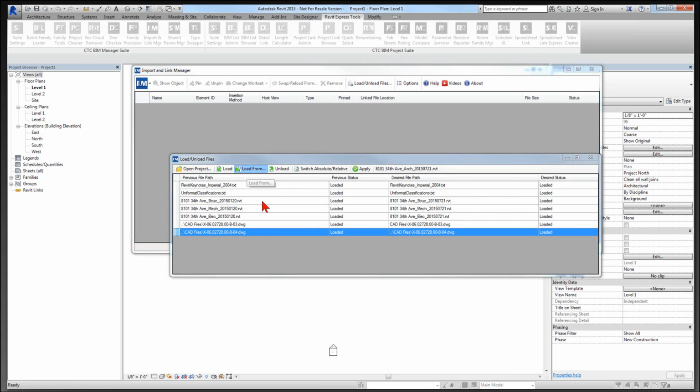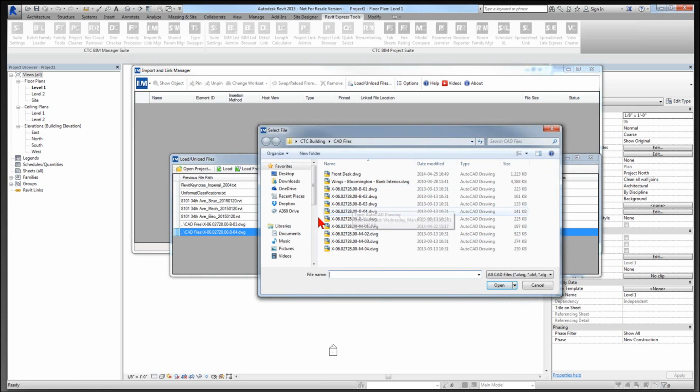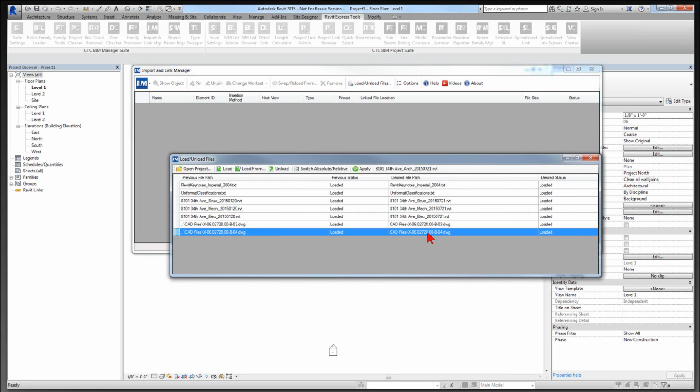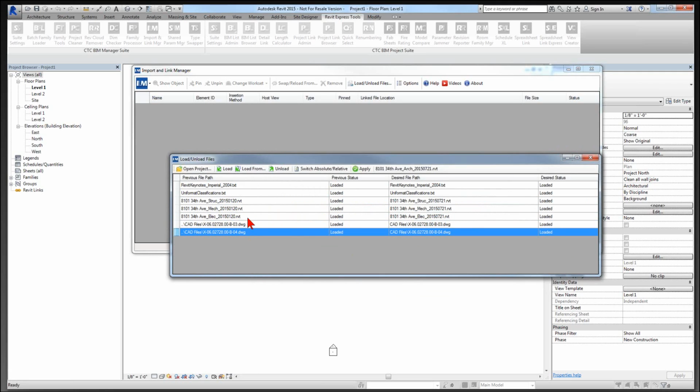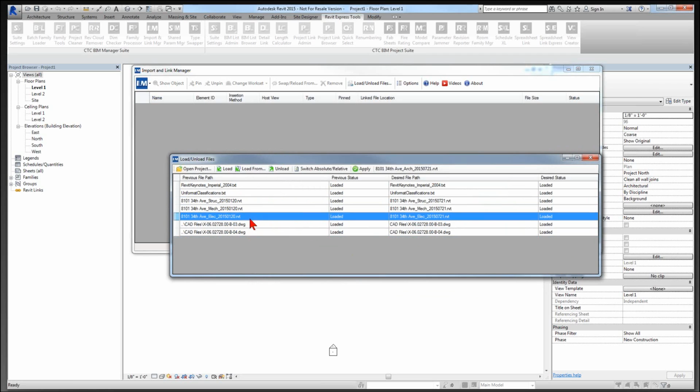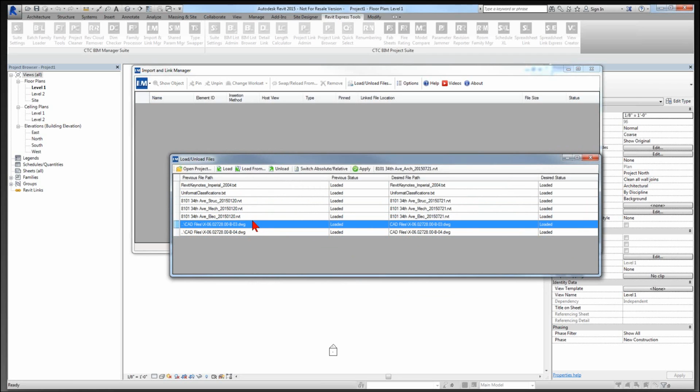And the same thing here, reload from, and I'm going to grab, that's the B04. I could grab that since I'm here, and I'm just going to make sure that it's ready to go before I load it in, before I even open it up, so that Revit doesn't sit there and take 15 seconds for each one of these links and try and search around and find something that it's never going to find. That way it'll make it open up lightning quick.